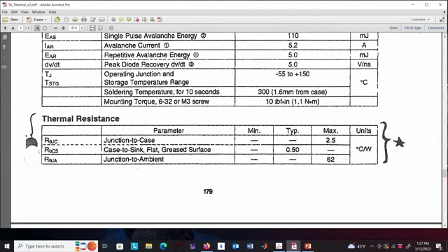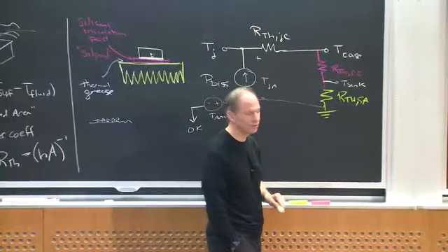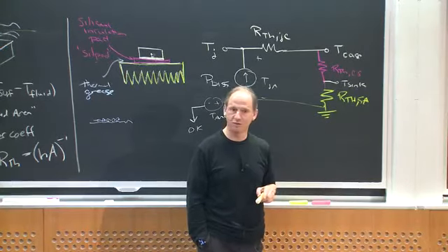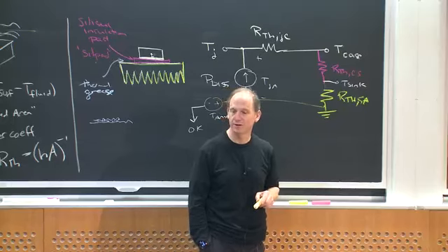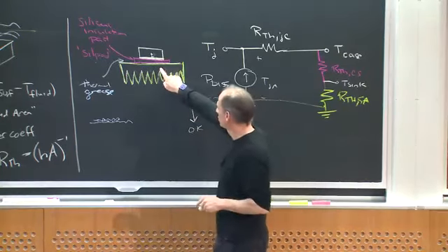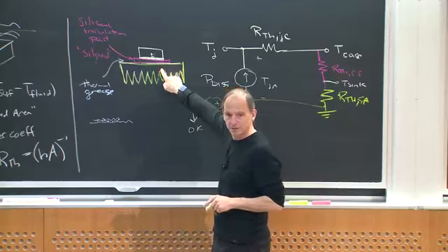And then they tell me, if you get just the right amount of thermal grease, and you do a really good job of mounting this down to a heat sink, so we're not worrying about any additional insulation pad here, it's another 0.5 degree C per watt between the case and the sink. That's if I don't need electrical isolation. If I do, I have to look up the thermal resistance of my Sil-Pad or whatever else I'm putting in there.